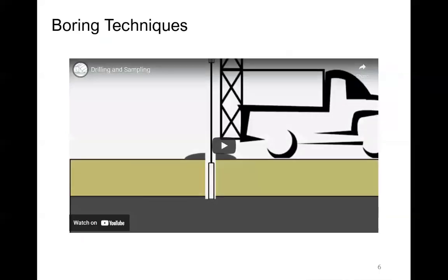So I have this little video, I hope it ends up playing, but it kind of illustrates the boring process and the sampling process. So 2 things to look for real quick. One, they'll talk about the type of soil conditions and the ways that they mitigate the potential of the void or the hole collapsing in on itself, right? If we go to the beach and we start digging a hole, eventually we'll get to a depth where the sand is just collapsing in and we can't dig any further. So if you're doing a boring and you're trying to collect a sample 100 feet down, then that's obviously an issue. We need to mitigate that. We need to add something to that hole so it doesn't collapse in on itself.